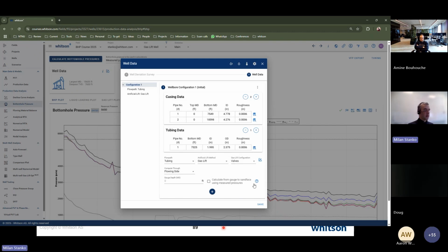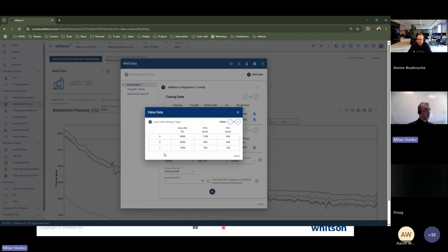Okay, and Mo, you can correct me if I'm wrong, but this option is in case the pressure calculations show that no valve works, maybe because you need a very high pressure to inject through that valve. Then it assumes that the last valve is always open, so whatever you're injecting will go through the last valve. If after that analysis of which valve should be open you find none, then you go through the last valve. Yep, that's correct.